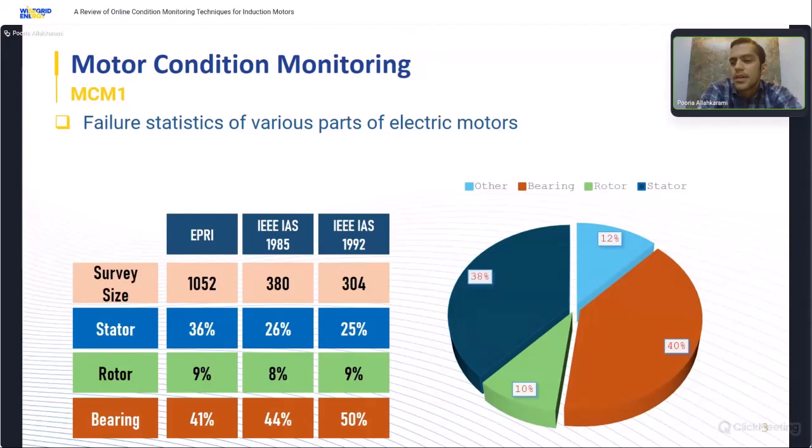These faults can be caused by a variety of factors such as external conditions, like abnormal loads or poor power quality of the electrical system, and human factors can also affect the faults. For example, improper bearing lubrication or frequent motor starts can lead to heating of the rotor and stator. But in some cases, the issues are unavoidable.